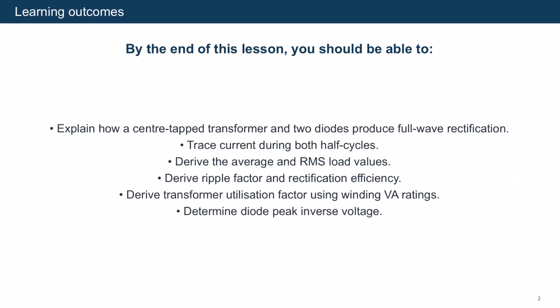By the end of the lesson, you should be able to explain the operation of the center-tapped circuit, trace both conduction paths, and interpret the load waveform. You should also be able to derive average and RMS values, ripple factor, rectification efficiency, transformer utilization factor, and the peak inverse voltage requirement of each diode.